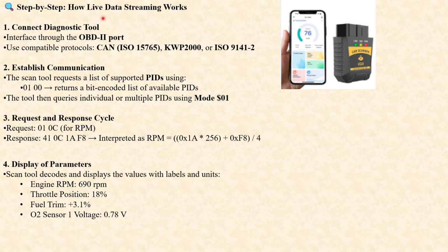Step by step, how live data streaming works. So we'll see how this live data streaming is carried out. First, connect the diagnostic tool interface through the OBD2 port, using compatible protocols: CAN ISO 15765, KWP 2000 or ISO 9141-2.